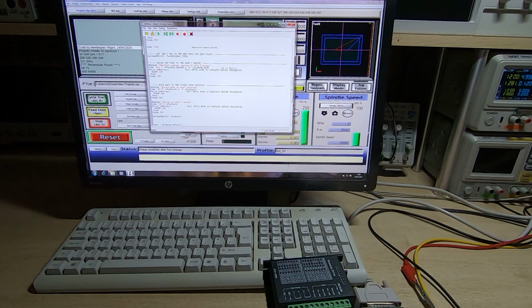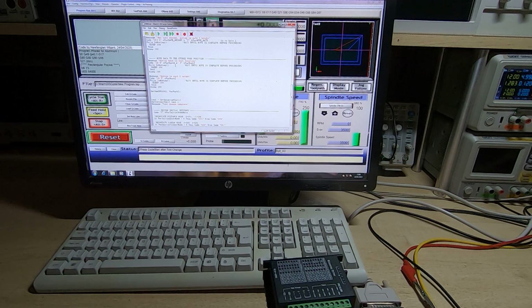When it does that, it effectively swaps the new tooltip location for the old one. In other words, it changes the offset in our G54 fixture so that the machine thinks that the tooltip is in the same place, and it then goes back to a safe Z height, so we can then move the tool back to where we want it without breaking anything.